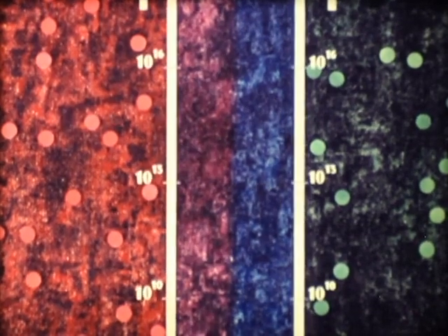In the vicinity of the junction, an electric field has been set up which acts as a barrier to the flow of majorities. Initially, during the formation of the PN junction, the barrier is very narrow, allowing majorities to diffuse and recombine from both sides. The result is a loss of majorities at both sides of the junction and thus an enlargement of the barrier. This enlargement causes a slowing down of the diffusion process until finally an equilibrium has been set up. Consequently, no current flows across the junction due to the two space charge layers which make up the barrier.